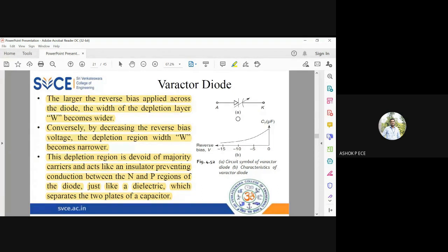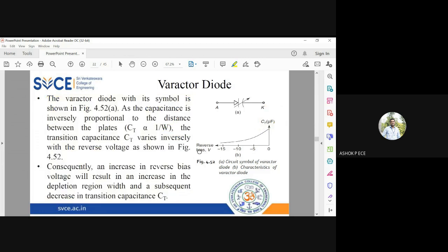Also, the reverse bias capacitance value is very small, in the order of picofarad. Fabricating such a capacitance is very difficult and not possible that easily. So in such a case, I can substitute that capacitance by a reverse bias PN junction diode. It will perform exactly the same function as the capacitor. The only thing is you have to keep a reverse bias supply constantly around the diode for it to function as a Varactor diode.